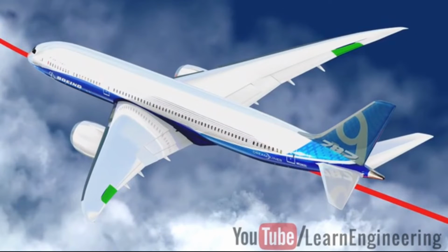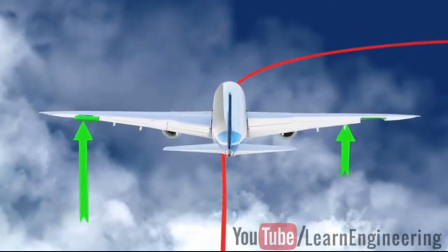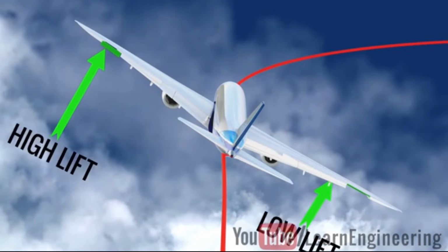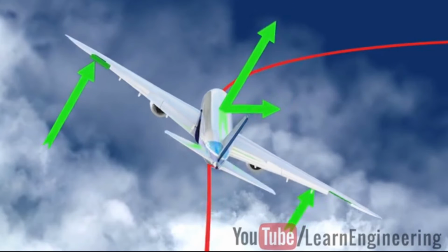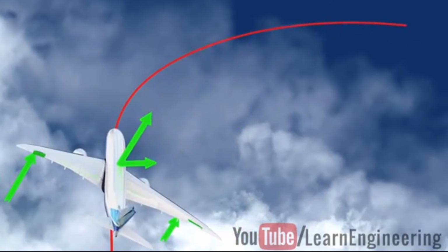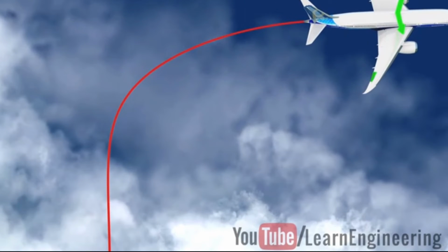Pilots just make one aileron go up and the other aileron go down. The difference in the lift force will make the airplane roll. In this roll condition, the lift is not vertical. The horizontal component of the lift can provide the necessary centripetal force to bank the aircraft. This way, the pilot can make a turn of any radius depending upon the angle of roll and the speed of the airplane.